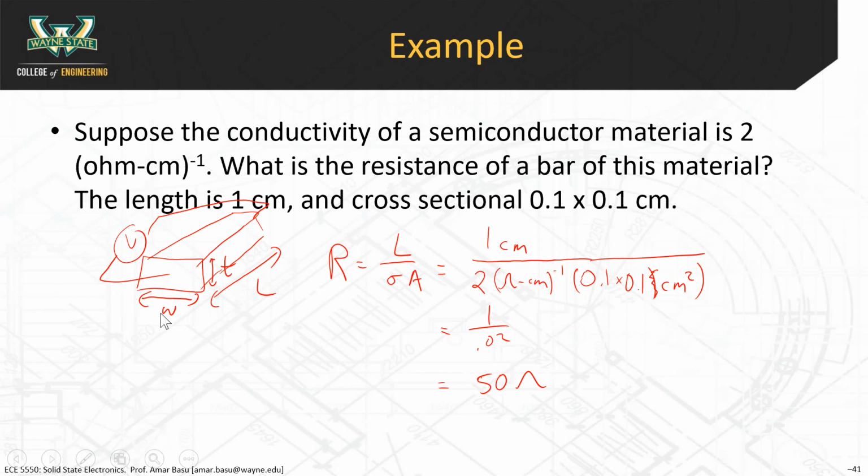The width is something that the CAD designer can control. The thickness is also within the control of the semiconductor engineer. The length and the width are what's drawn in the CAD model. The thickness is determined by the semiconductor process.